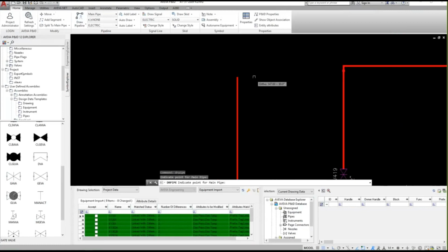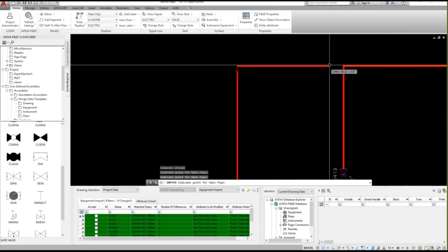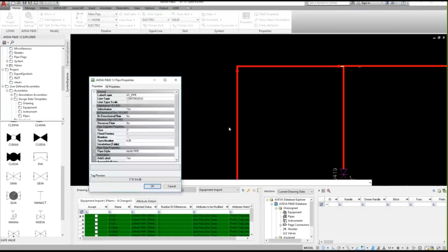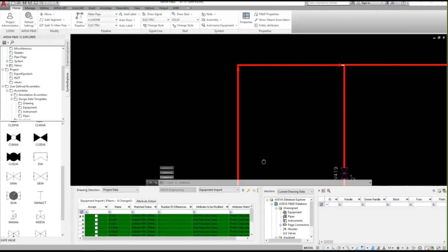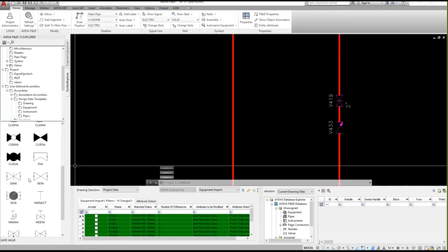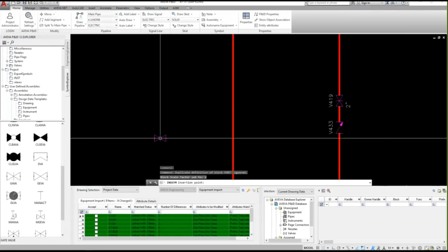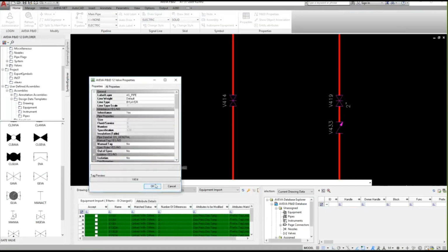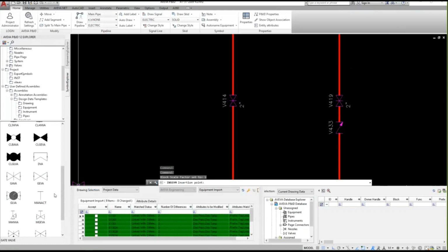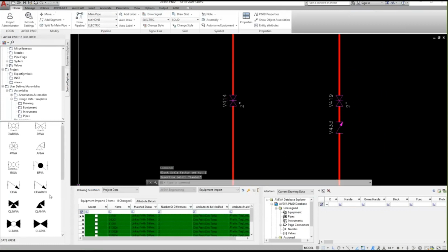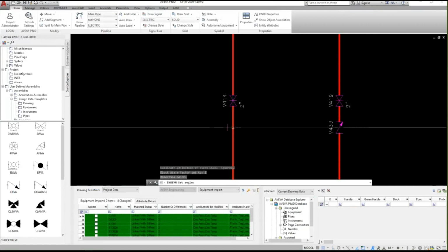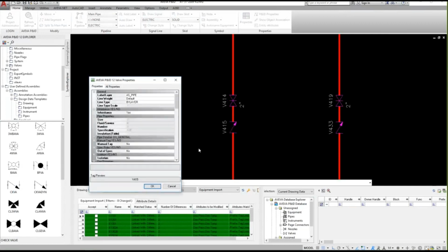And what we'll do is we'll just come up here, connect it to this line, inherit properties of this line, cancel it so it uses the same line number. And then we'll enter a block valve and a check valve. So here again, tag and size. And then what I want is just a check valve. So where's my check valve? And we'll put my check valve on here as well. Okay, so we'll say okay.